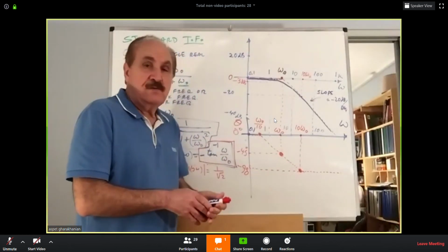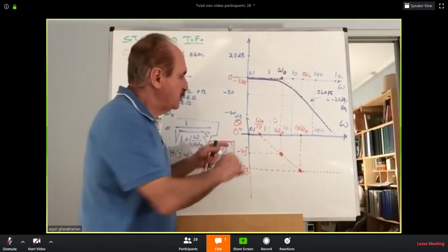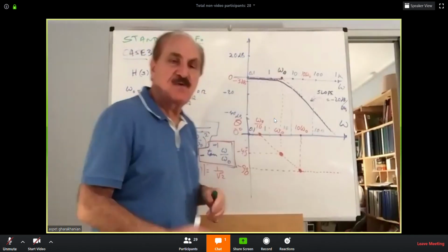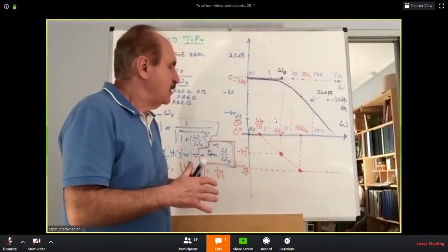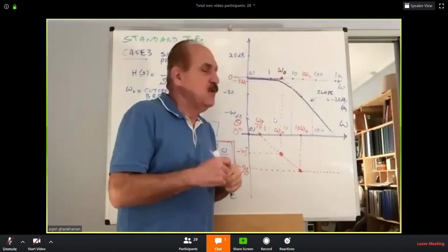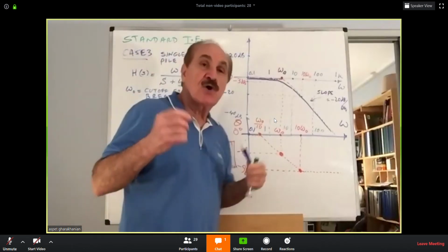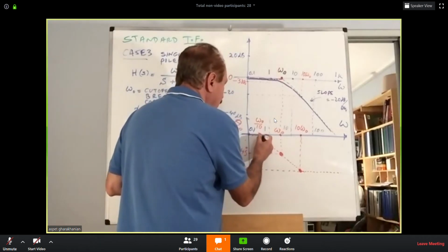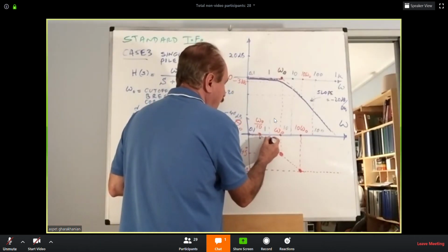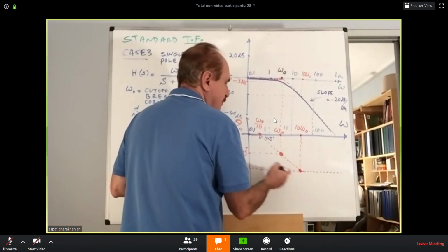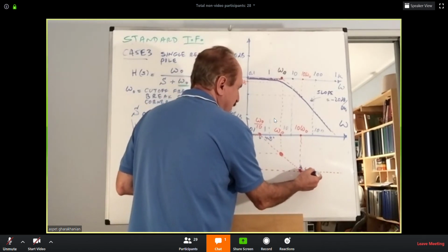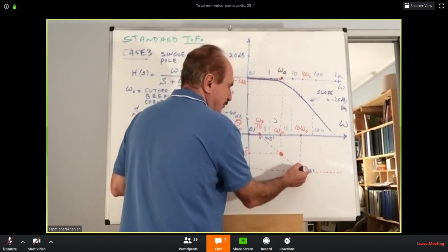So the designers, when they want to create a smooth curve for the phase angle, if necessary only, can modify by the corrections that we know how much they are. From this end, we need to go down 4.8 degrees. From that end, we need to go up by 4.8 degrees, roughly speaking.